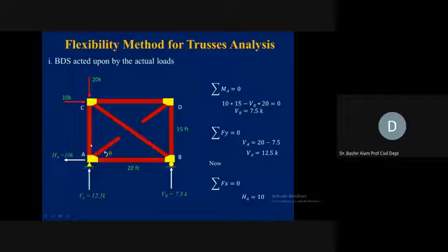So we have found the direction. What will be the magnitude? It is balancing 12.5, so the magnitude will be 12.5 and it is in compression. Member AC is now analyzed. You don't need to draw this A and then show the vertical member, the horizontal member, and then HA and VA, and then write the equilibrium equation. Straight away by observation you can do it. But remember, this observation comes from experience. You have to now practice these problems.